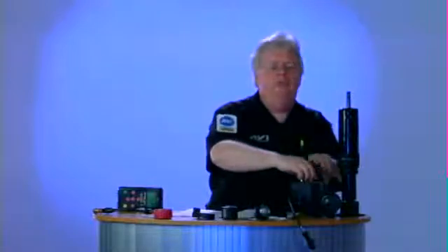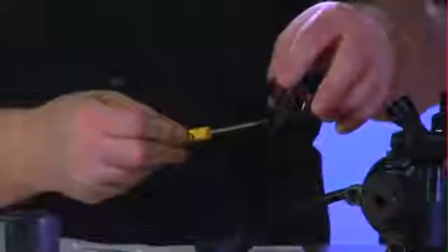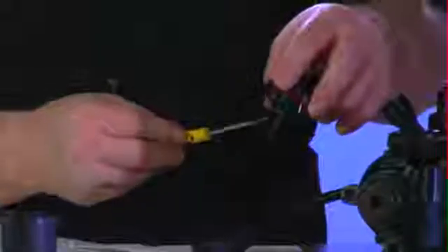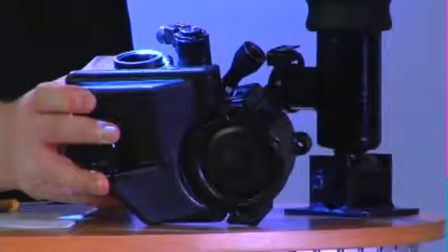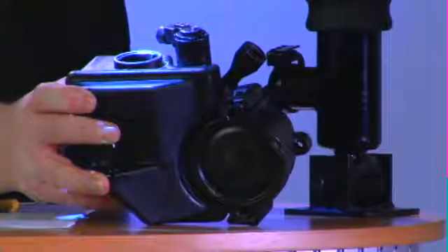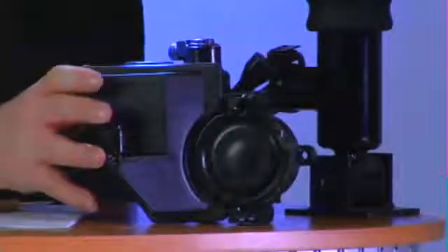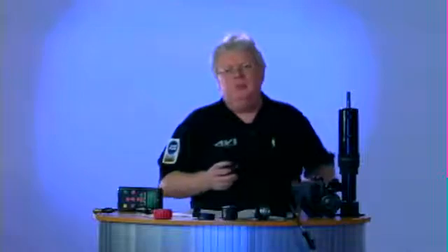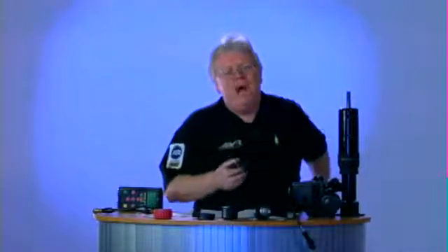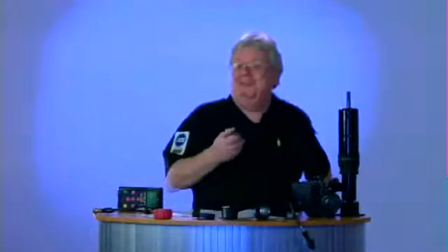When you look at the fluid, don't just check the level. Now, most vehicles have a graduated dipstick on the end of the cap, but not all. If you don't have a graduated dipstick on the end of the cap, simply take a flashlight and look down in the pump with the engine off, warm engine, but engine shut off. The reservoir should be about 2/3 full. Or just measure it. Wipe it off like a regular dipstick, put it back in, pull it out, and see where it is.